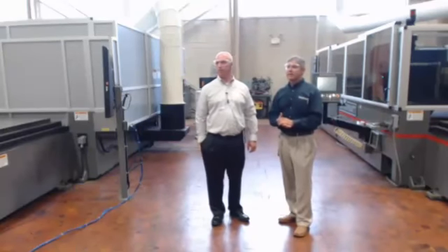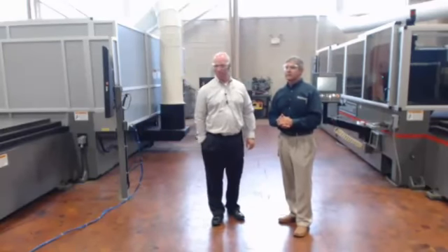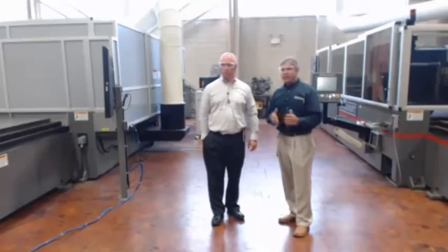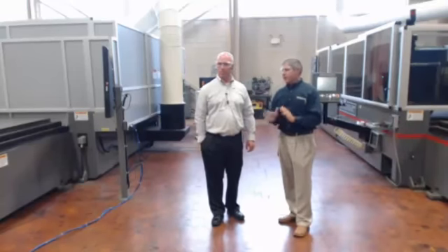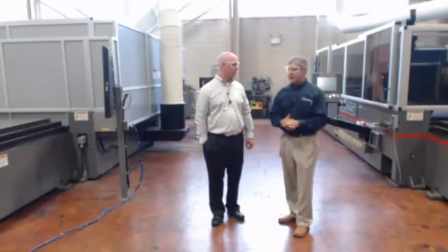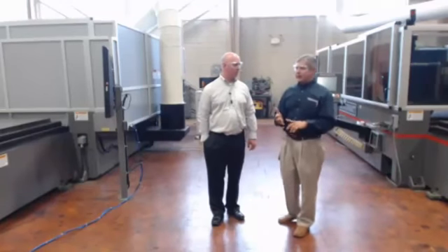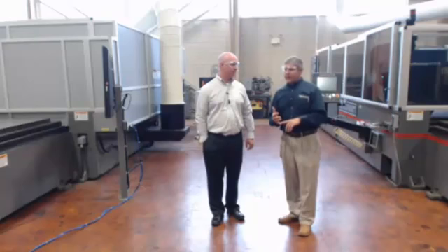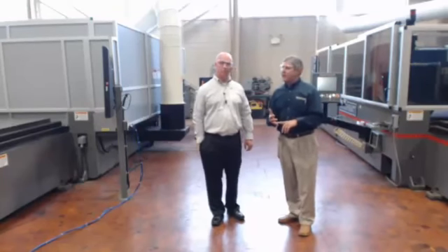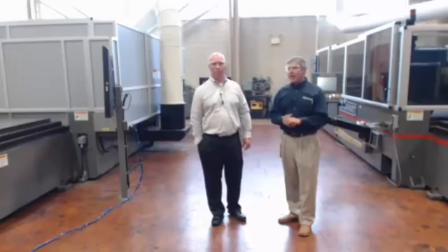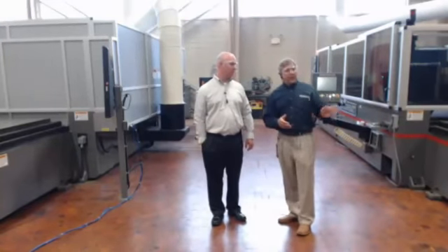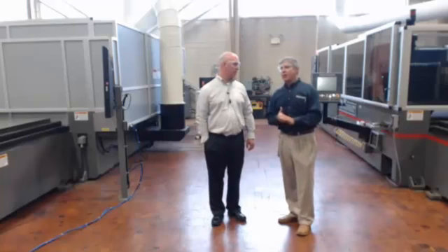I had a question on the CL940, just asking about capacities of the machine as far as thicknesses and types of material. When I mentioned the comparison of the two technologies here, there's certainly a difference in the enclosures and other things. There is a difference also in the capacities and feed rates. On the capacity side, this fiber machine is rated at 1/2 inch for stainless, mild steel, and aluminum. We can cut a little heavier here on the CO2, with 1 inch on the mild steel.